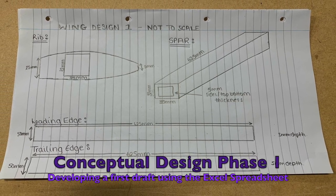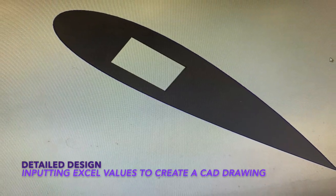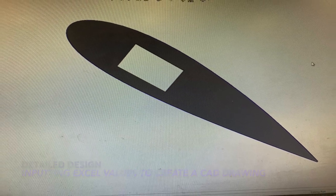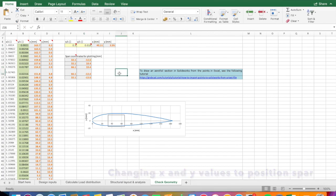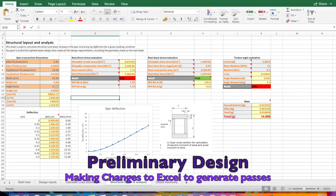A first draft was developed using the primary dimensions in Excel. Following this, detailed design occurred and a rib was developed in SolidWorks using the primary dimensions. The spar was positioned in the rib by changing X and Y coordinates. A sample spar was then manufactured and tested. Changes were made to Excel to generate passes and meet the requirements.